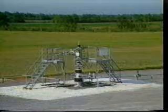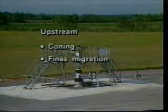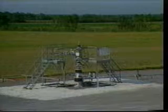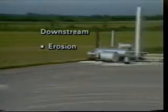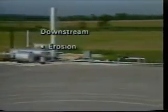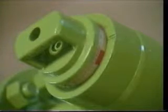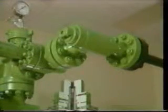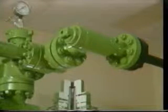The rate at which a well produces has far-reaching effects, both upstream and downstream of this equipment. Upstream concerns include possible formation damage caused by factors such as coning or fines migration. Downstream concerns include possible excessive erosion of equipment such as valves, tees, and so on. Correct selection and operation of the choke is very important and allows us to prevent or minimize problems which could occur from poorly controlled production rates.